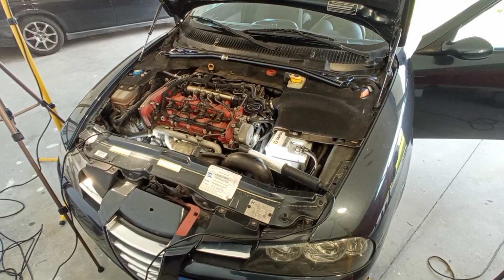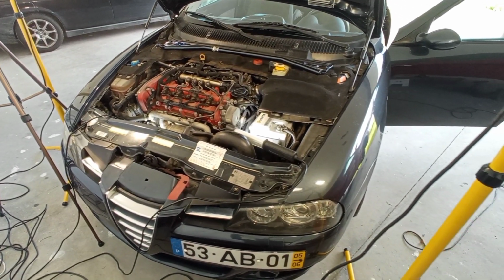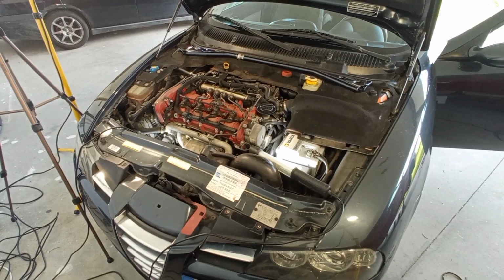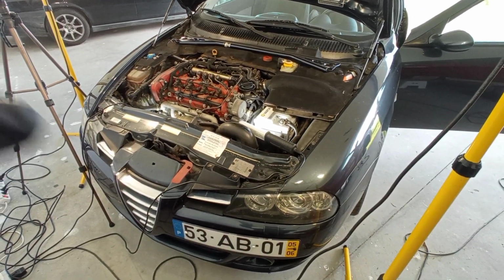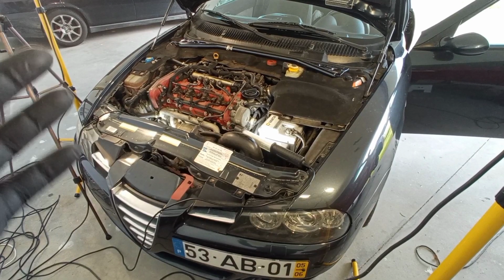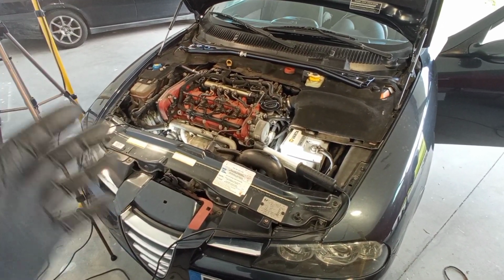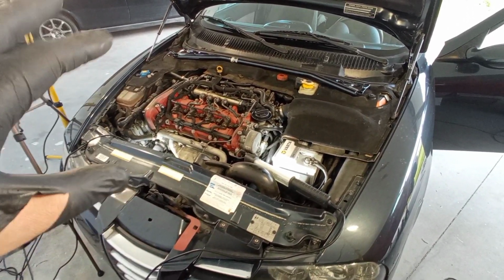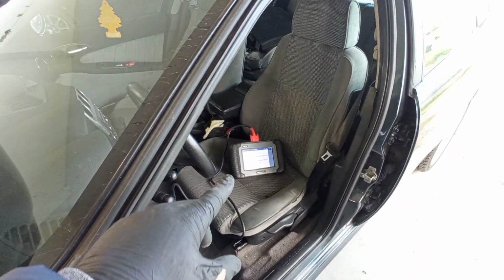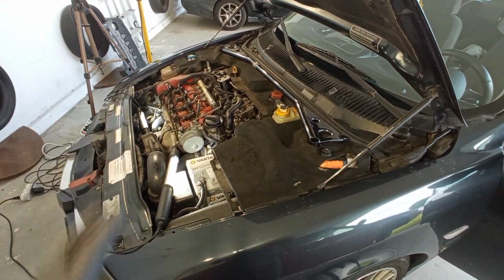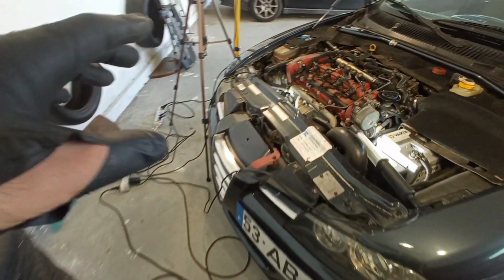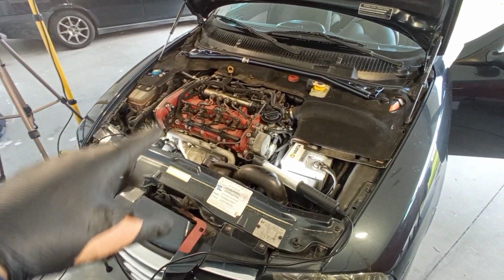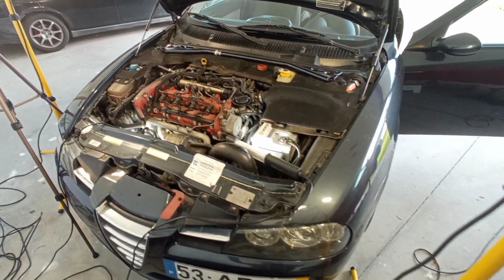Today on this video, does your common rail engine not start? Well, it cranks, but does not start. Today on this video, I'll try to explain everything you need to know so you can see what the hell is the problem. Now, this engine is in perfect working condition, so I will disable some stuff here so we can see on diagnose with my very old Autel machine over there what are the signals that you may have to see to know what is the problem. I'm talking about crankshaft sensor, fuel pressure regulation, etc. So let's do it.